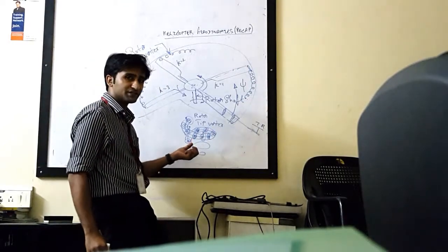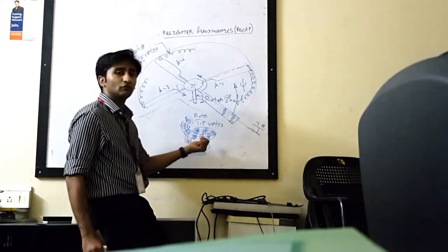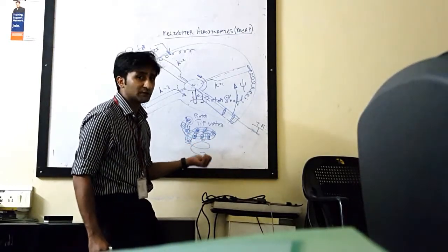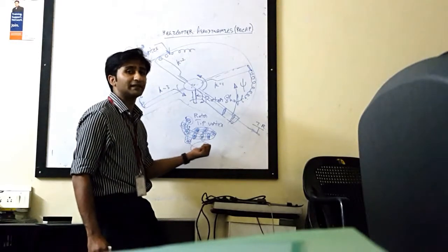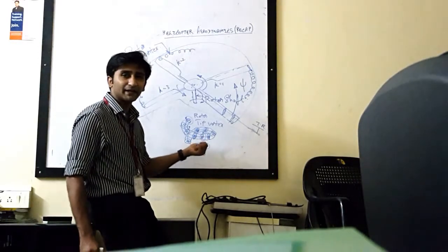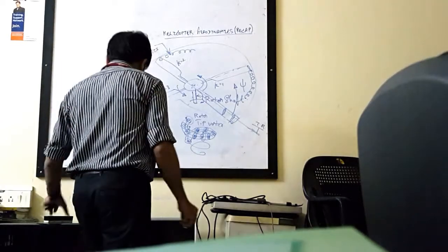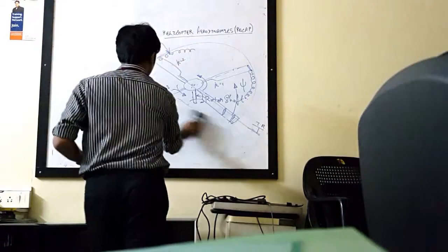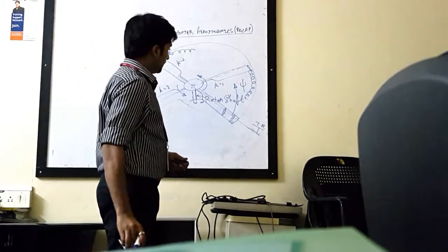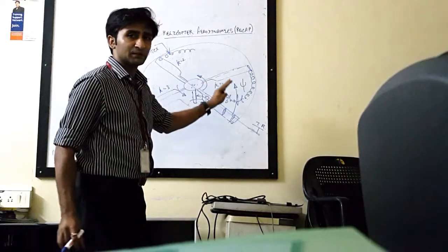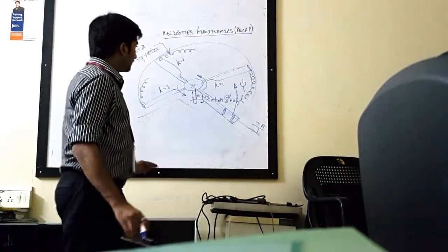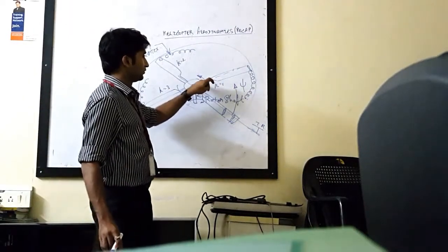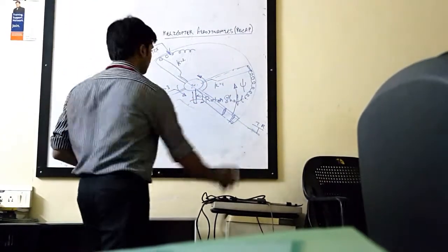Greater the amount of lift which is needed, greater will be the vortex strength. And greater the vortex strength, greater is the time required for the vortex to die, or the vortex decay time will increase. Okay, so now we have understood some aspects of helicopter rotor wakes. We will come to the actual assembly of this blade to the hub, and what other controls are there.